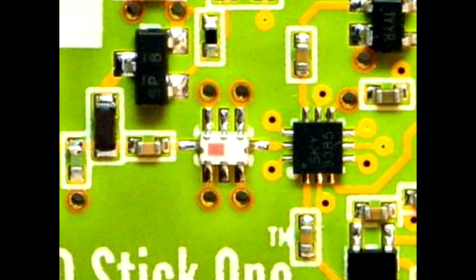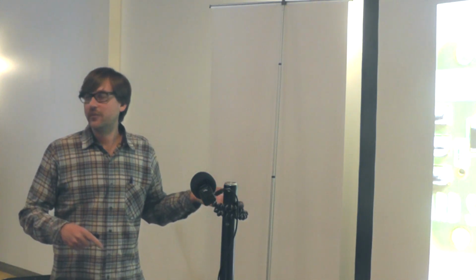But this is a filter. Again, I'm replacing what could be a mess of inductors and capacitors with a filter. This is a low-pass filter designed for the 900 megahertz band. 900 megahertz is the highest frequency range that is supported by Yardstick 1. So I use a low-pass filter to cut out any harmonics that are above 900 megahertz, which is quite optimal when you're using Yardstick 1 in the 900 megahertz band. It's somewhat less optimal when you're using Yardstick 1 in lower frequencies, but it's a heck of a lot better than nothing. So I have an RF filter.